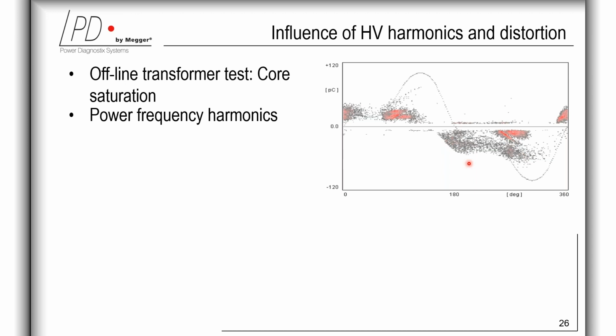And this is related to a distortion of the cavity discharge pattern. The larger scattered pattern in the negative half cycle directly shows this distortion. And in the positive half cycle, with a higher availability of electrons, it is split into two patterns.